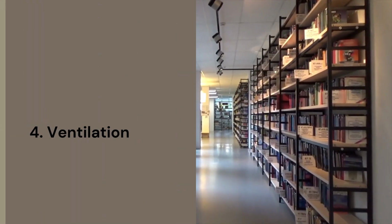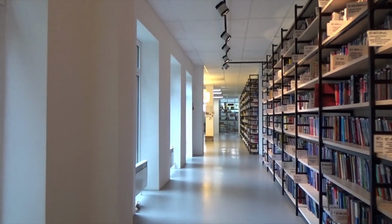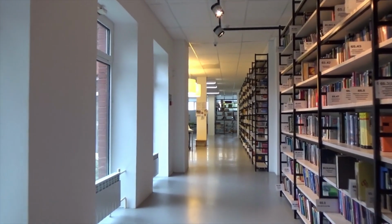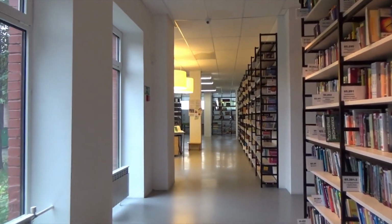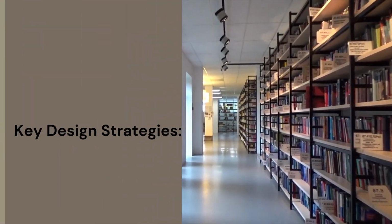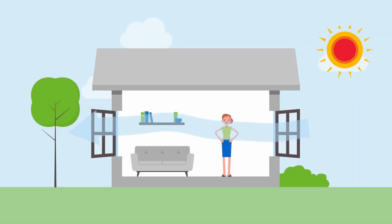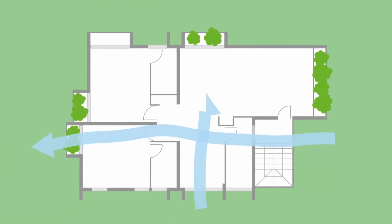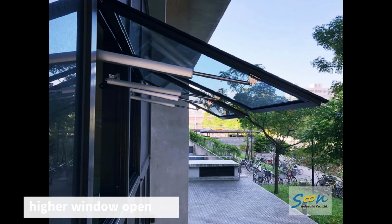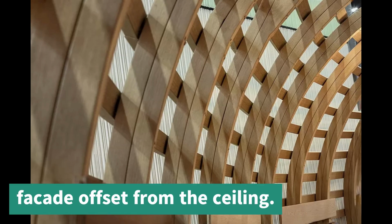4. Ventilation. Playing with the existing natural ventilation can eliminate the need for external ventilators. Afternoon heat buildup can be avoided by providing openings that encourage air circulation. Key design strategies. 1. Ensure cross-ventilation in which cool air enters through one opening and warm air exits through another. For cool air entrance: windows, louvers, open facades. For warm air exit: roof vent, higher window openings, facade offset from the ceiling.